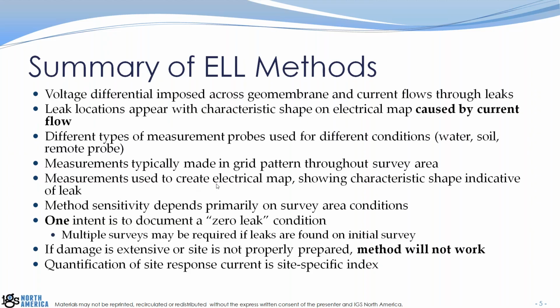So starting with the first section, summary of ELL methods. You have a voltage differential imposed across the geomembrane, and the current flows through leaks. Those leak locations will appear with a characteristic shape on the electrical map caused by the current flow.